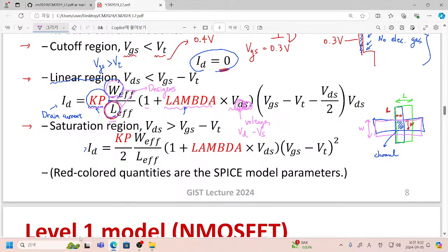We are pointing to the value of the drain with the reference of the source. So usually in the case of a MOSFET, source voltage is sometimes regarded as 0 when it is grounded. In some cases people just use it that way, but rigorously we have to use the difference between drain and source voltages.